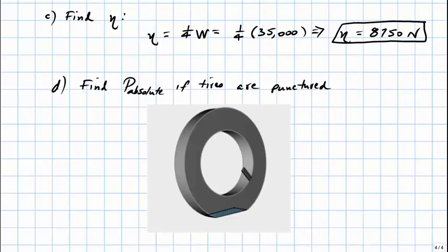It's important to note that the absolute pressure will push against every surface on the interior of the tire in an outward direction. And so the absolute pressure at this location is directed this way, which is an outward direction. On the other hand, the absolute pressure on the inner surface of the tire will be directed in the opposite direction, which again is an outward direction.